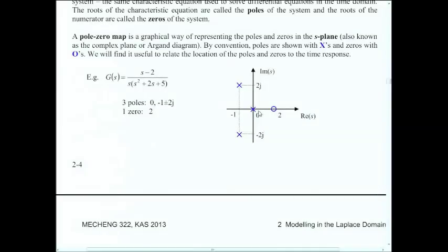And that's enough information for me to actually tell you stuff about that system. If that was a real system that we modeled, a spring mass damper system, I could tell you that it's marginally stable, meaning if you gave it certain inputs, it would go unstable, but if you gave it other inputs, it would actually look quite benign. I could tell you that the response would have some oscillation in it, and generally it would be underdamped, so you'd get this kind of ringing, and then it'll die.